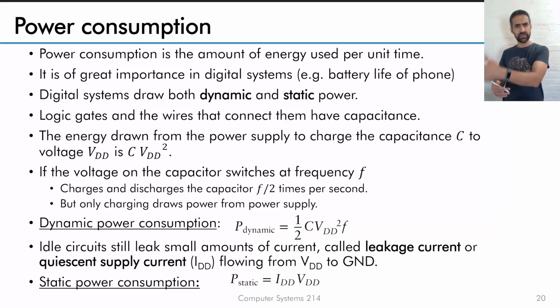That's obviously partially the chip, partially the circuit, so you have to probably measure it, but they do give the capacitance for the chip in the data sheet. That's the capacitance. That is the voltage that you're switching, and this here is the frequency at which that switch occurs. Now, obviously, if you change just once, there's no frequency, it's just a singular switch. But if you have a voltage level that continuously goes up and down at a specific frequency, then this is the frequency.